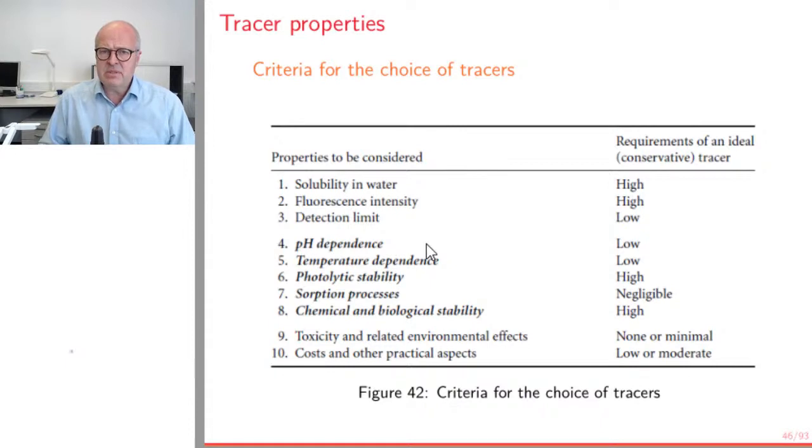And in the lab, someone expert, knowing the device very well and the tracers very well, measured the sample. So everybody familiar with measuring fluorescent dyes knew that he had to actually buffer the water to produce a stable pH at 8.2 to have the best possible measurement of uranine. So he did it by adding a buffer substance, creating a pH of 8.2, and he got a very nice, sensitive, reproducible measurement at